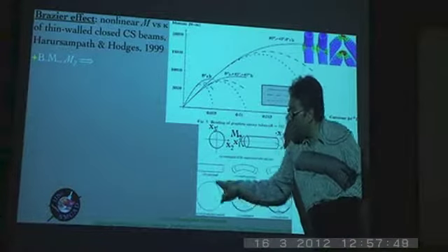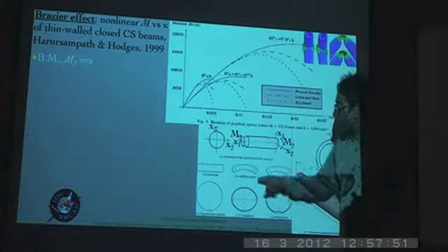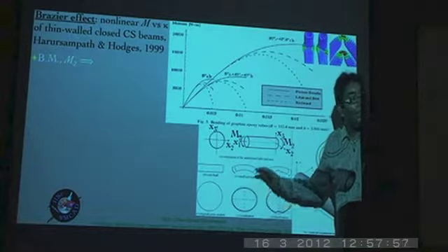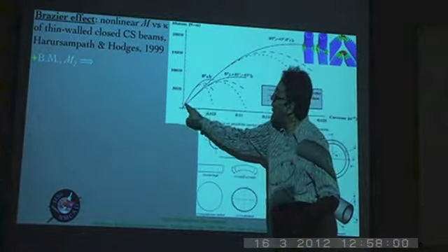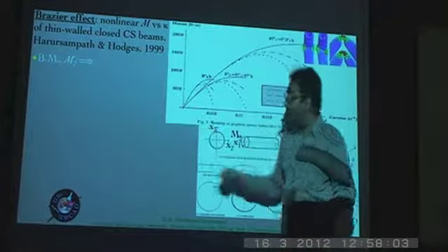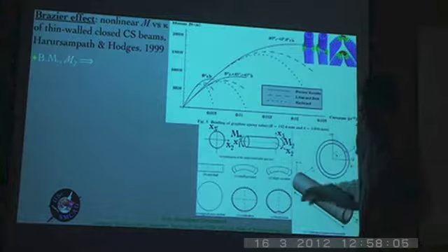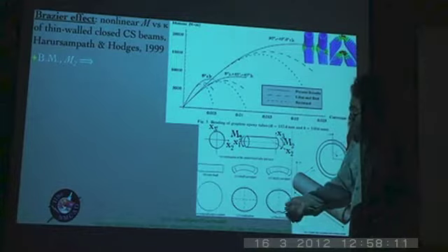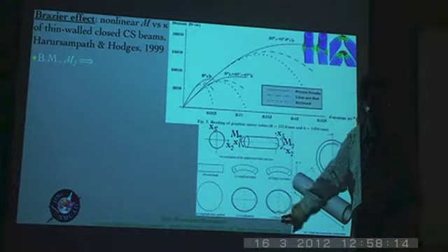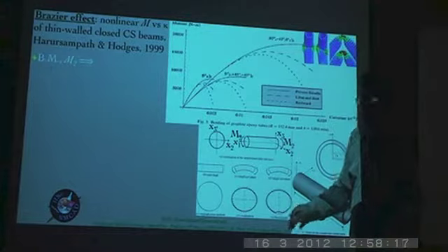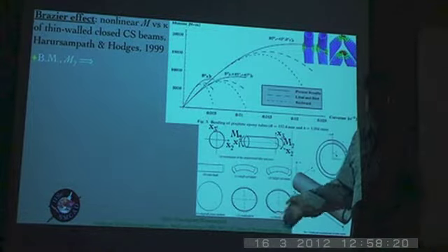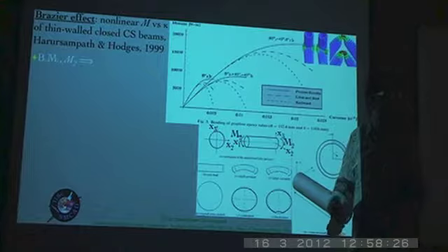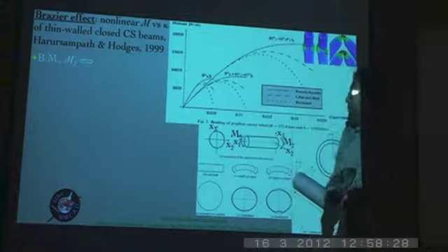At zero load, it remains a thin-walled circular cross-section. As you have small curvatures, you have a little bit of flattening, hardly any change in the bending stiffness, and that's what you see. It's almost a straight line in these areas. But then as you start increasing the curvature, either this is an example of a local instability that I was talking about, where the portion in which there is compression, small portions of that can undergo a kink. But if this were not to happen and material failure were also not to happen, then you would have a limit moment instability where you have this kind of behavior.